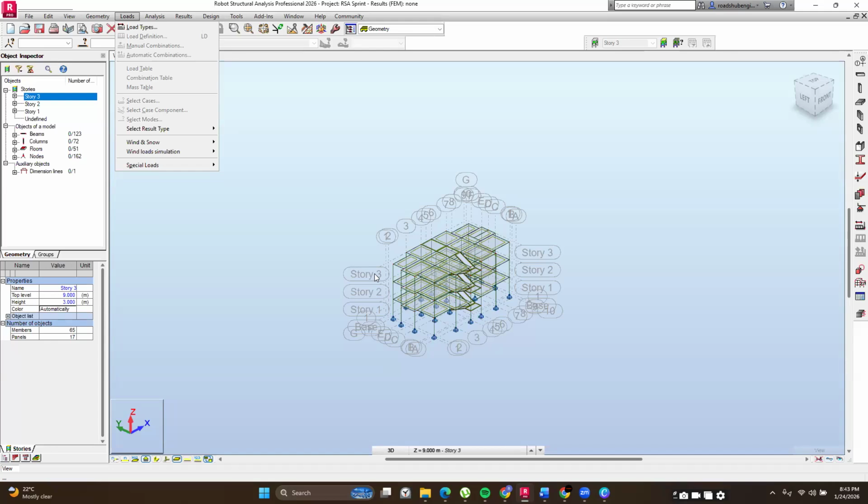You tell the software that these are loads, say, emanating from the walls. These are loads emanating from the finishes. And then, apart from that, now you have to define the magnitude. So after you've told the software I have wall loads, then you have to come and tell the software that this is the magnitude of the load that is coming from my wall. So the first stage that you are in is in defining the type.